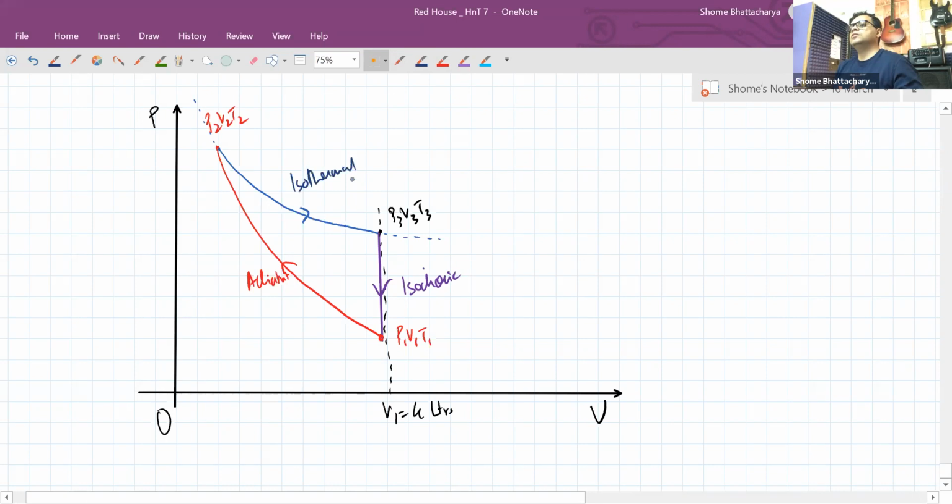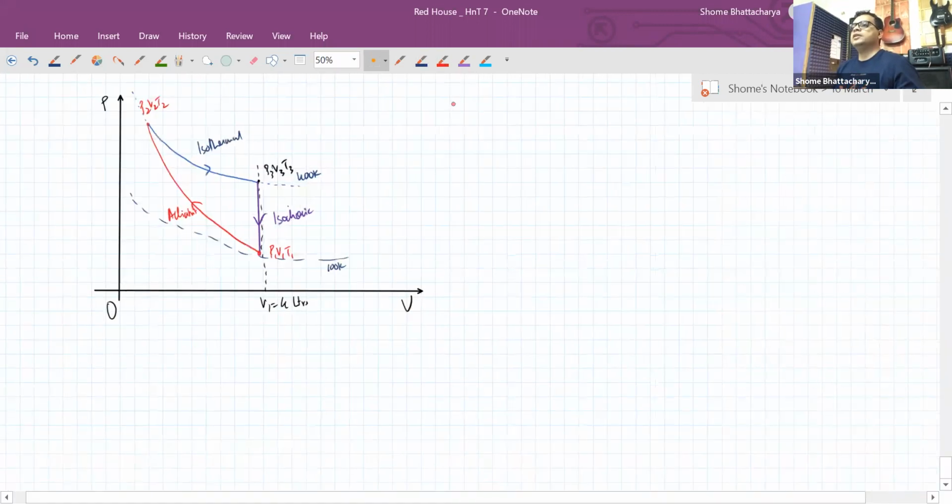This is isochoric, this is isothermal. Okay. So basically you're cutting between these two isotherms twice. Once you're cutting from the lower isotherm at what was it, 100 Kelvin to the higher isotherm at 400 Kelvin, but adiabatically. And then later you're cutting back from 400 to 100, but isochorically. So that is this.